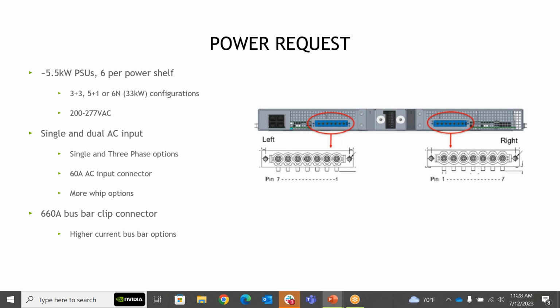So, since it is integrated in the power supply, it does have impact on capacity per supply. It's kind of a trade-off. My experience with using just the ATS version, depending on the infrastructure, if you're switching multiple megawatts from one feed to another within the, I'll say, 10 to 20 milliseconds of the holdup time of the power supplies, that's a significant hit on the upstream infrastructure.